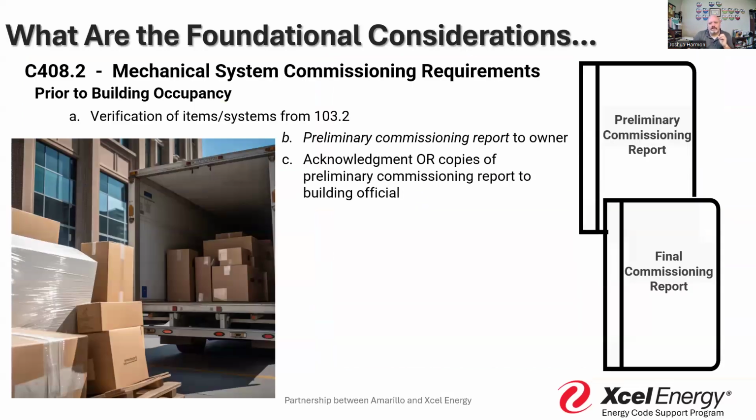When we think about what's expected as part of the commissioning report for those multifamily systems following the commercial provisions, there's a requirement that we provide not only verification of everything that was included in our plan and our details, but also a preliminary commissioning report. Before we occupy, before we issue that CFO, we need to see a preliminary commissioning report on those multifamily buildings, because that tells me how well this system is performing.